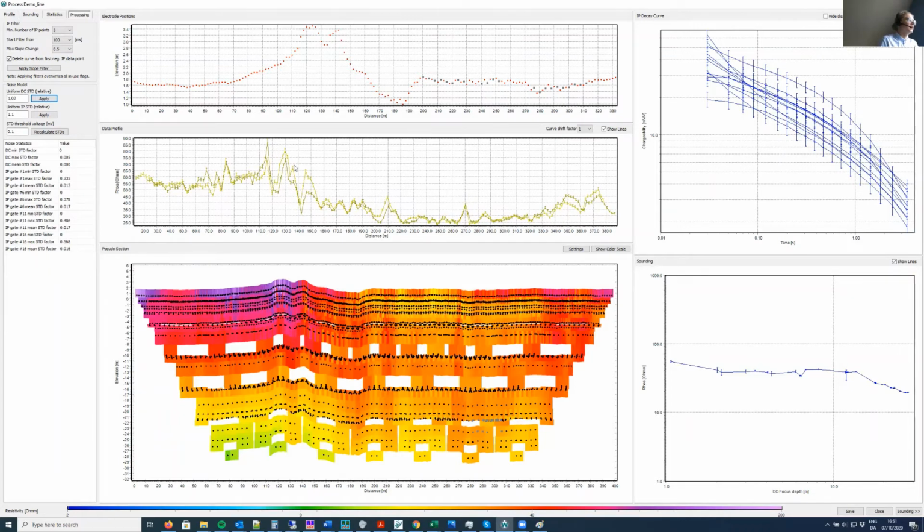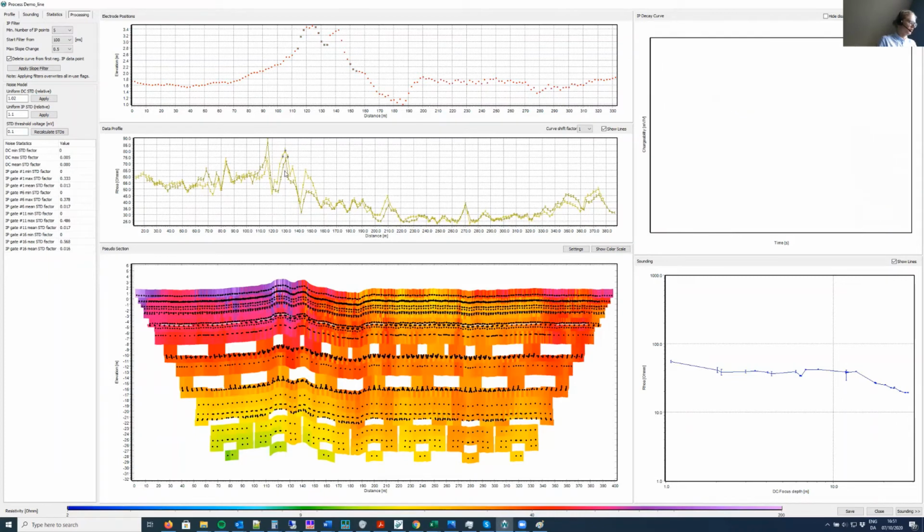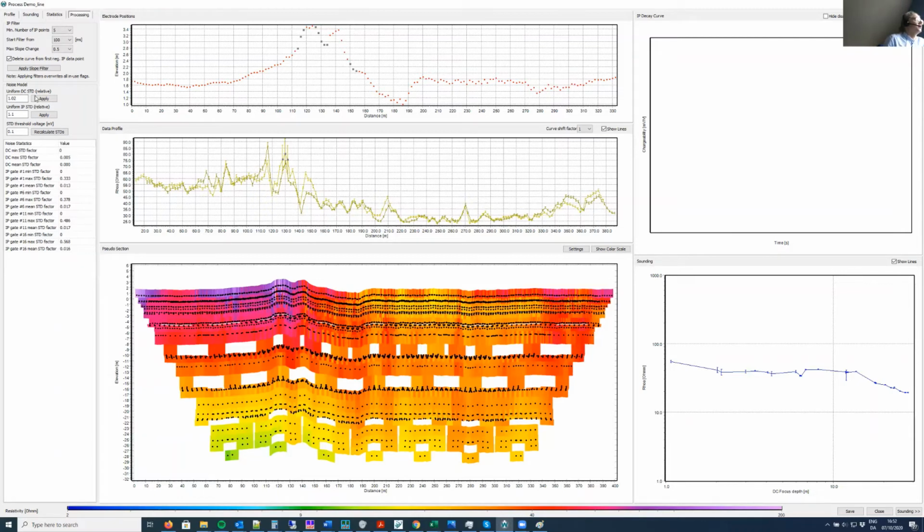You can do that by selecting a data point or a few data points, and then you can use the Alt key together with the number keys. So now I'll, for example, press Alt and 3 together. Then we have increased the standard deviation of these points to 30%. And then if I click this button again, you can see that this doesn't affect these points. They will still have the manual value that I've put in. I'll just change it back to 10% here.